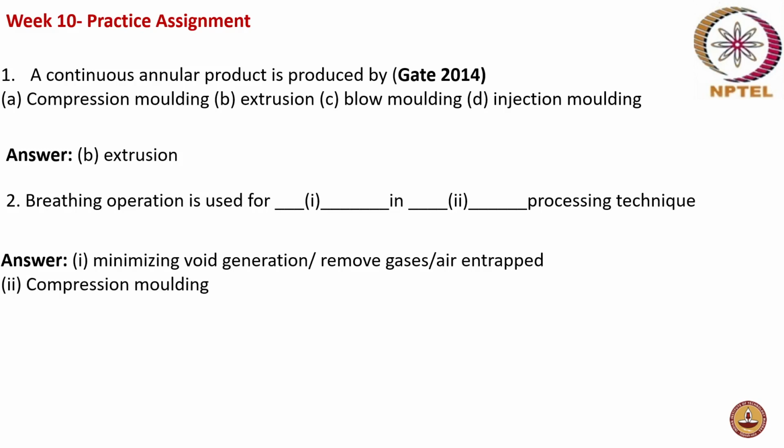is performed in a compression molding process where once the liquid polymer enters into the compression mold, and then the two platens are brought together, the platens are held for some time and then opened for some time and then closed back, so that the entrapped air or moisture can be removed and thus helps in minimization of voids.